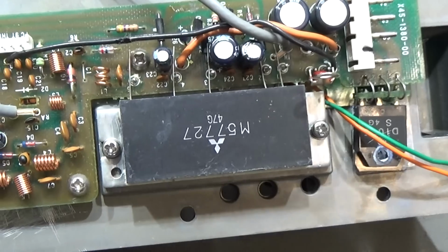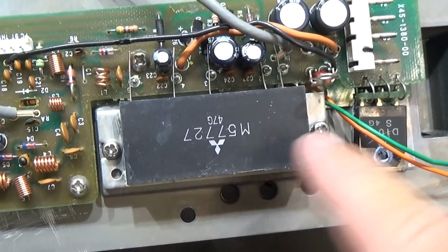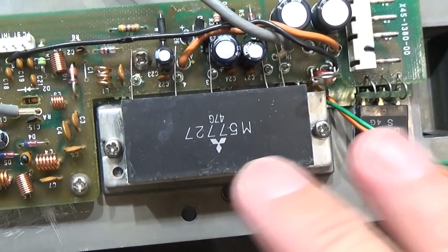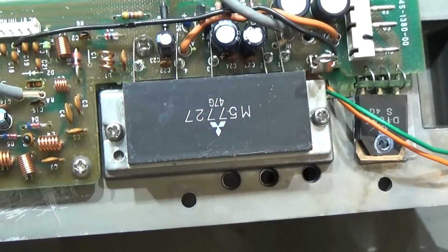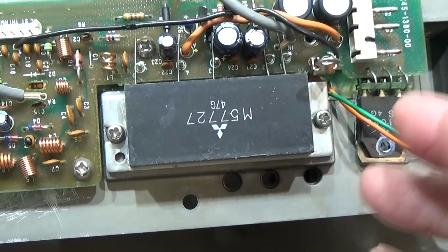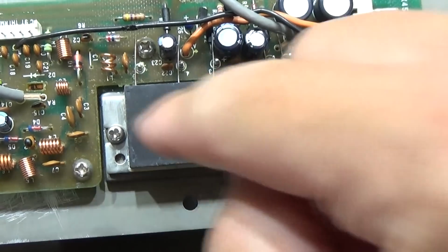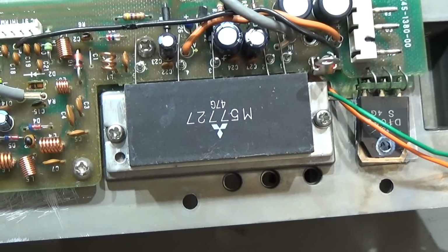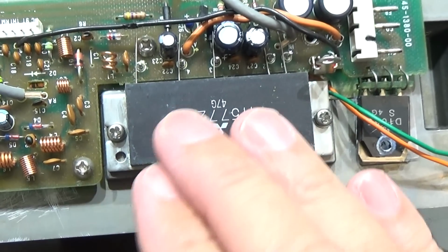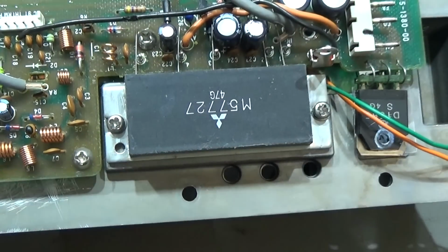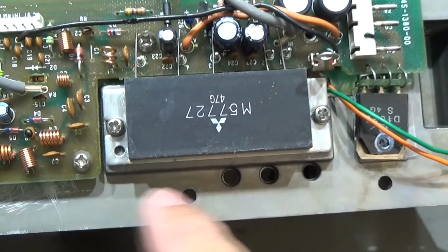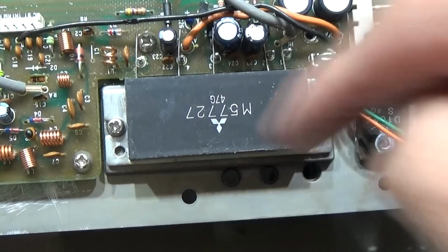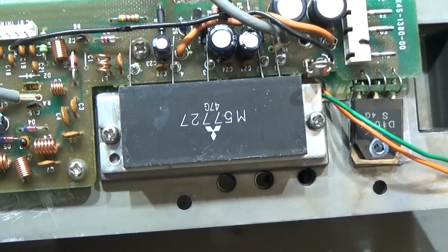Okay, anyways, let's try it out. And as you can see, I've put in here the screws to have good alignment, to really have no stress on our wires later on. So that is the way you should do it. Put it in, align it with the screws, align the board itself, and then you can solder.